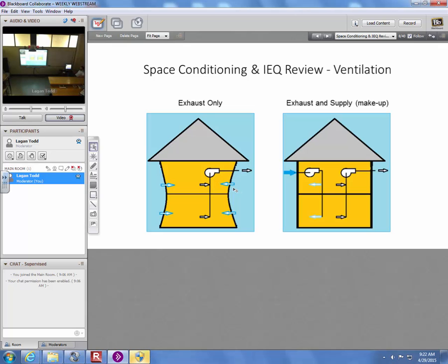And what would be a greater concern to me is if you have an envelope leakage point that happens to be near plumbing. Typically we try to keep plumbing to interior wet walls and not in the exterior walls, but some buildings do have plumbing in or very near exterior walls. It might be that you have an envelope leak, like you saw in my house when we did the blower door test. The cabinet under the kitchen sink had a pretty major infiltration point.